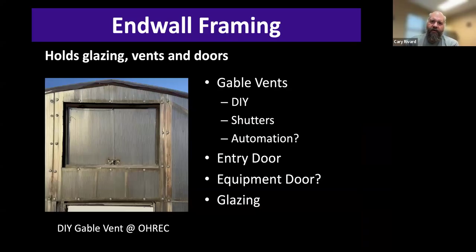Now, I think one of the most important things to put in an in wall is the gable vent. And unfortunately, I see a lot of high tunnels without gable vents. But as I mentioned before, they're really helpful, especially during the wintertime for ventilating that tunnel. And during the summertime, when it's really hot, you need pretty much every resource available to ventilate and cool that tunnel. This is a nifty DIY gable vent that one of our student workers actually designed and built several years ago. And we'll talk more about it when we get to the in walls webinar, but I just thought it was a really creative way to do it. And there's lots of ways you can get creative with some of this do-it-yourself stuff.